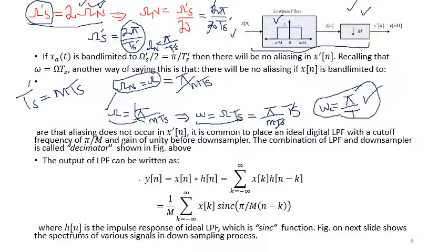And in the time domain we say the output, y of n, equals the input convolved with the response of this system, right? So let me represent it by h of n. So the output y of n equals x of n convolved with h of n. Or we can also write it in the convolution sum formula. So we say summation k running from minus infinity up to infinity. I hope this is very clear to you because you have done this so many times in signals and systems, right?